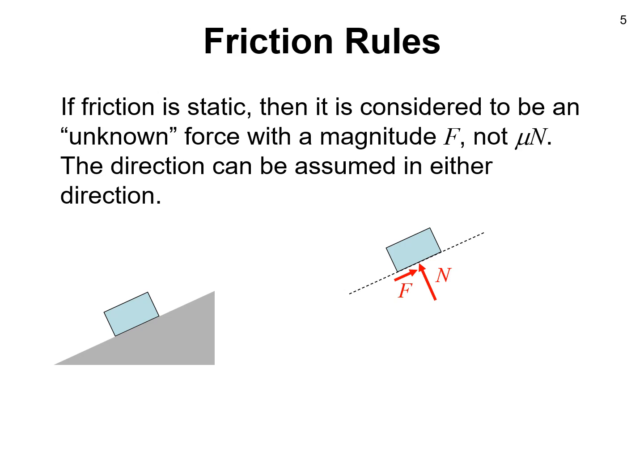And maybe we don't even know which way it's going. In this case, I've pictured it pushing upward, but it turns out that you would be equally correct, certainly at this level of the course, to draw the frictional force in the other direction. What we'll see later is that eventually you would write equations and you'd solve for those forces. And if you had your force in one direction initially, you'd get one answer. And if you did it in the other direction, you'd have the negative of that answer, and that would be equivalent. And we'll see that later when we get to that point. But for now, just realize that you can draw the friction in either direction you want, unless there's something specific to tell you otherwise.